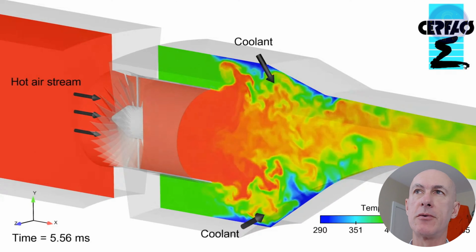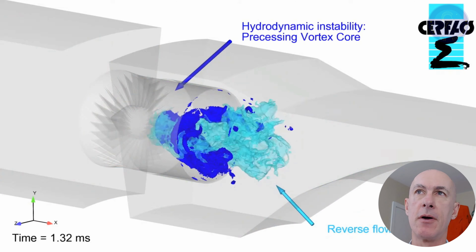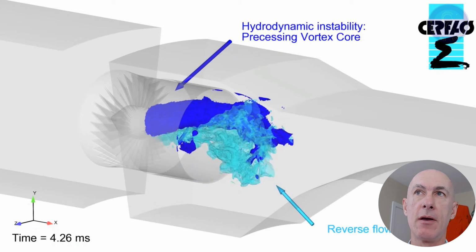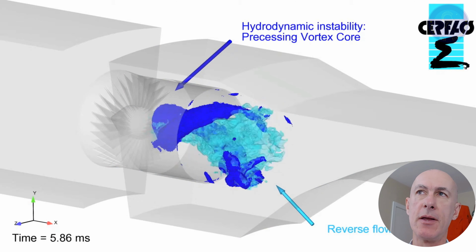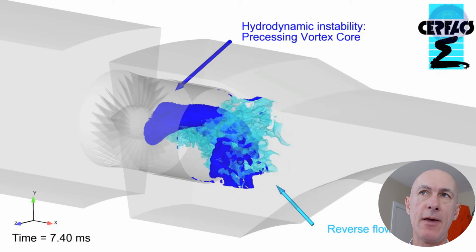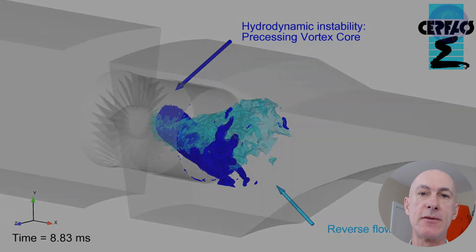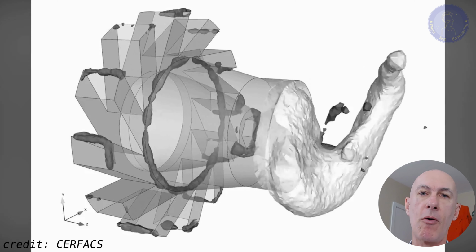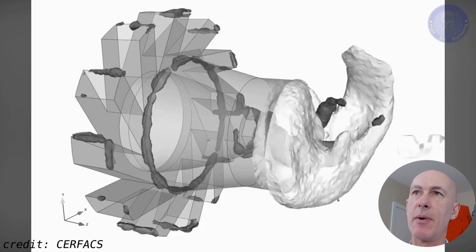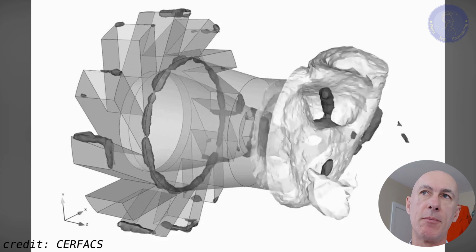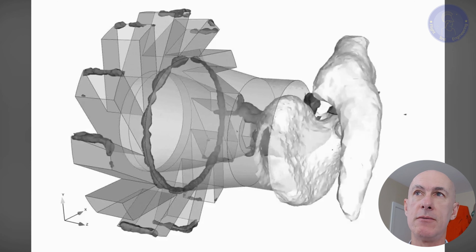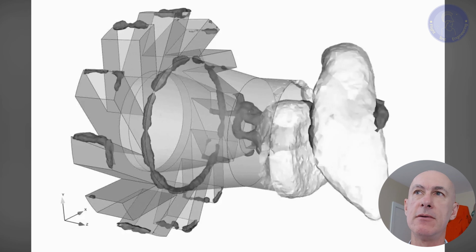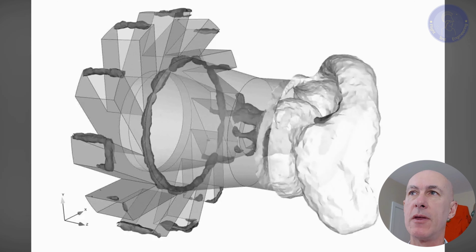Another parameter that we need to control is the fuel-to-air ratio. Too rich and it will not completely burn and will generate soot. You might say, but turbines operate on the lean side, generally with excess air. Yes, but what really matters here is residency time. Remember that aircraft engines need to be small, light, and compact. So the combustor has limited space, which leads to limited time to burn the mixture. On the other hand, too lean and the flame might extinguish. So there's a balance here, and the FADEC needs to take care of keeping the mixture within parameters.